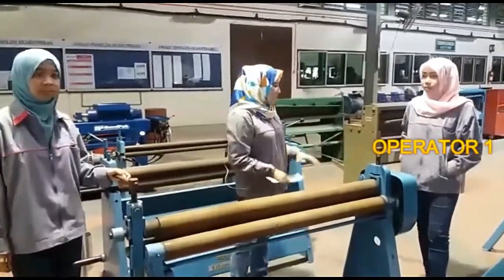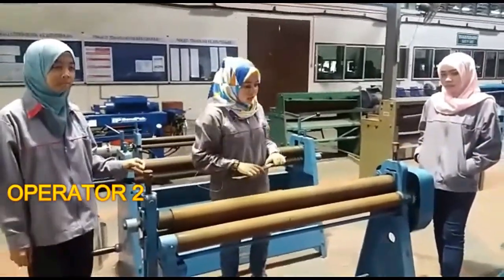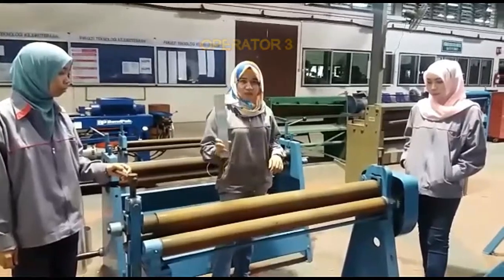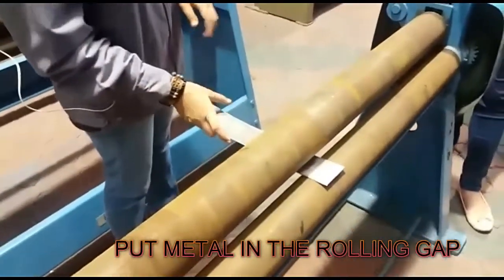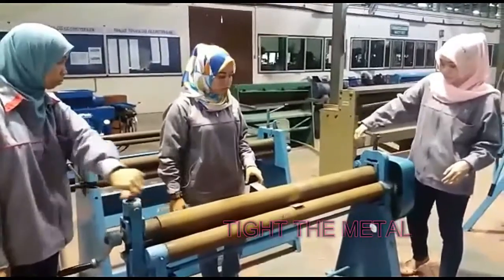This is the first operator that conducts at the left side, and this is operator 2 that conducts the right side. And the third person conducts the sheet metal working at the center. So firstly, push the sheet metal into the rolling. And then operator 1 and operator 2 must tighten the sheet metal by this upper roller.